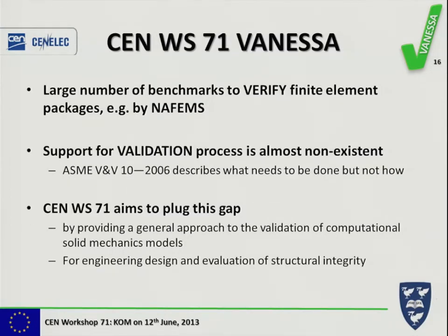So let me just say a few words now about CEN Workshop 71, or nicknamed Vanessa, and why we're doing it. There are a large number of benchmarks around for verifying finite element packages, particularly those provided by NAFEMS. And when you buy a finite element package, you would hope that the vendor has already verified that it's solving the appropriate equations in an appropriate manner. But there's very little support for validation and almost no process described to allow you to do it. The ASME V&V guide tells you what needs to be done, but not how to do it.